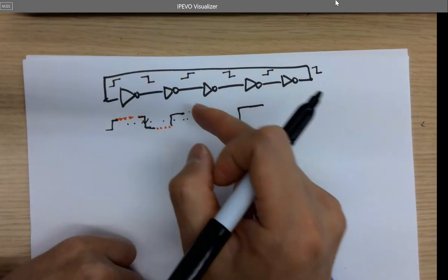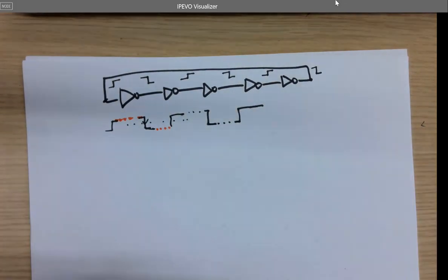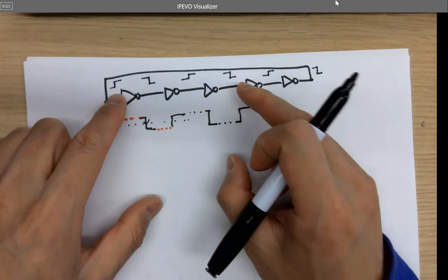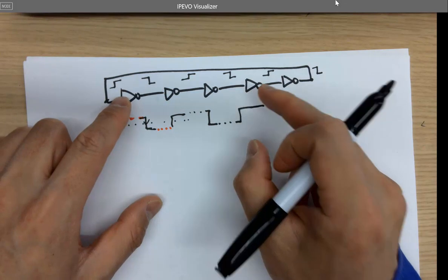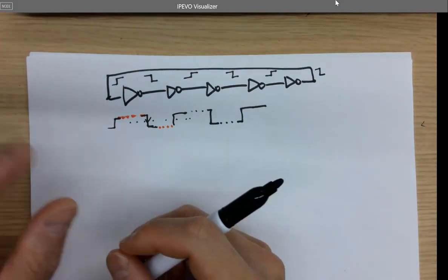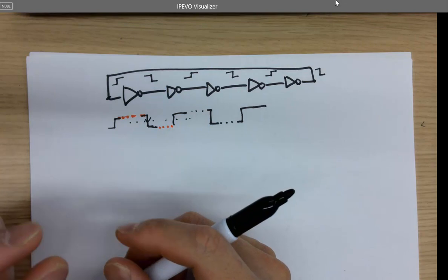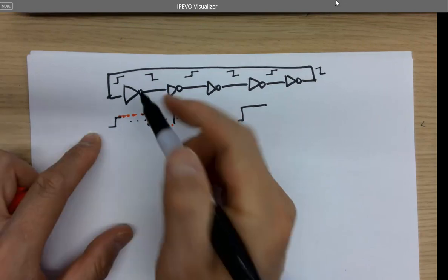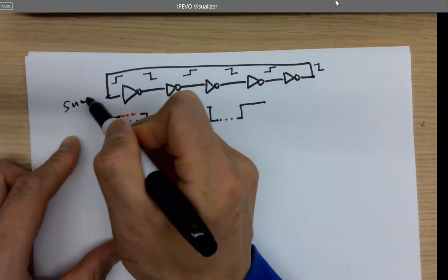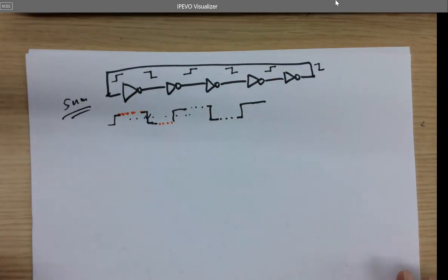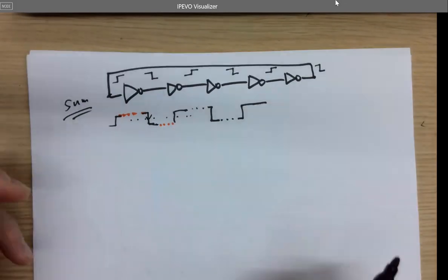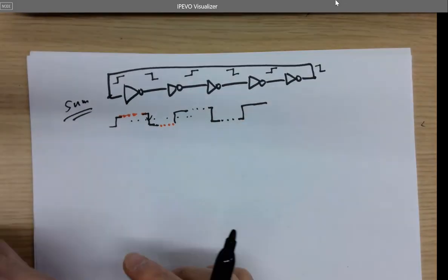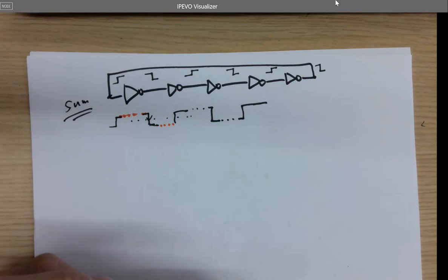And a lot of times you do need to put an odd number of inverters in a ring like this in digital circuits, because you can create a super tiny oscillator. Remember, in microcontrollers we had all these crystal oscillators on the board. It's huge. But just use the inverters, for example, like the 5 nanometer technology. It's just at nanometer level, and you put a number of inverters in the ring, it will create a signal, a clock. A lot of times it can be very accurate, depending on the calculation.